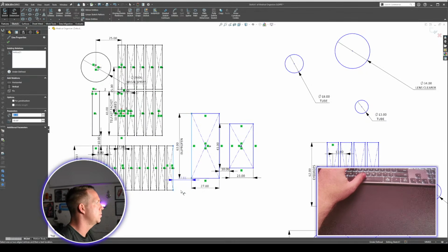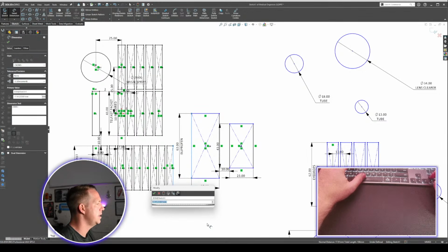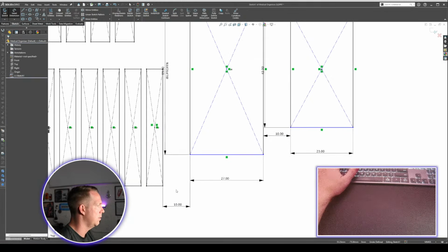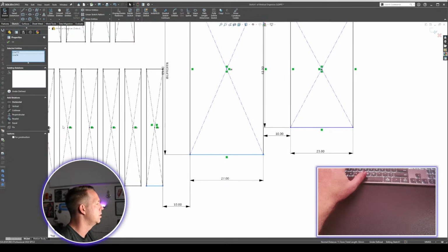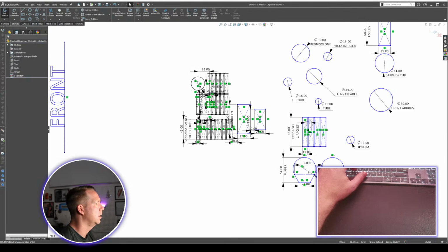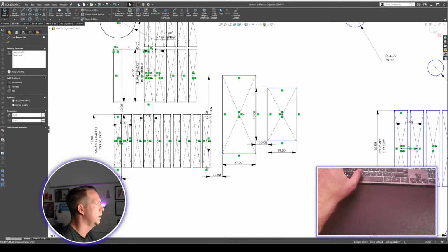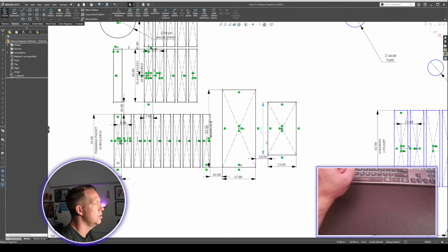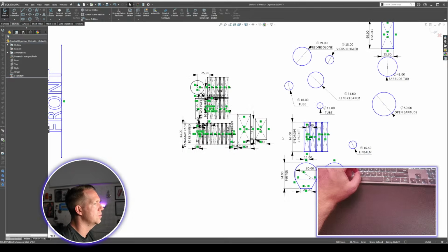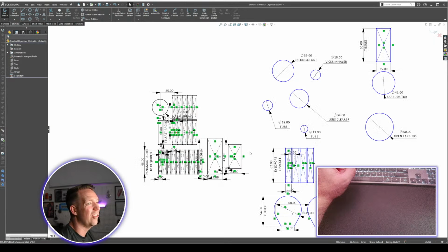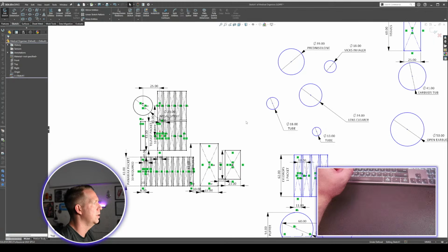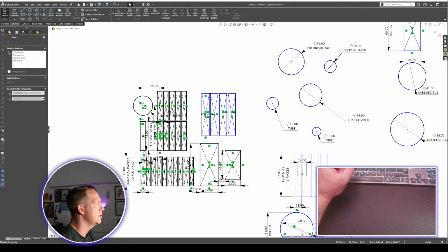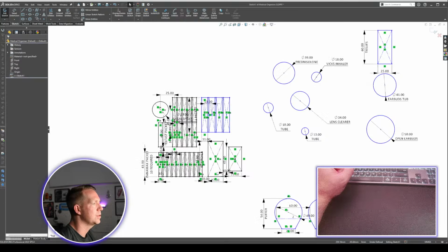So what I'm going to do is just put some space in. I'll put 10 millimeters and I'm going to line it up with the bottom edge. So get both of these lines and make them collinear. So collinear will get them to line up. And so you can see those couple are all starting to group together now. And so we're starting to get an idea of how the whole thing might sit. Now we can start to piece together what's going to fit in the gaps.